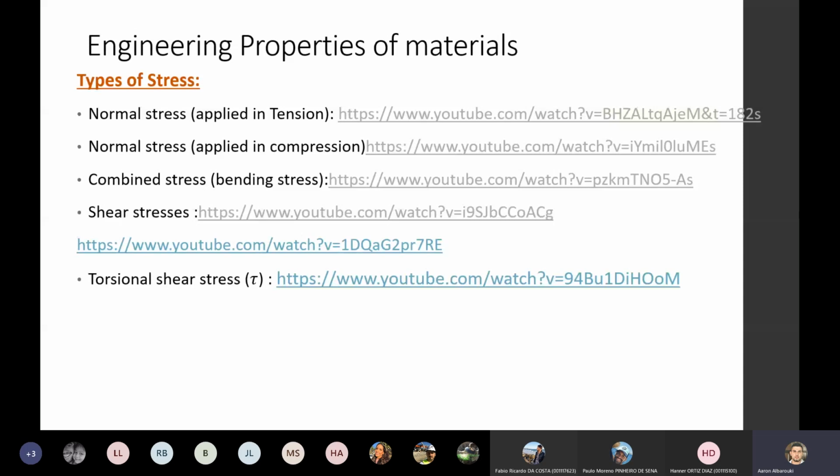Two, there are some additives we can add to concrete. When you talk about concrete, guys, think of concrete as a chemical reaction. Concrete is not a material. You're putting different materials together and creating a chemical reaction, and concrete is the outcome of this chemical reaction. So the slower the chemical reaction, the more time you give it, the stronger it is.